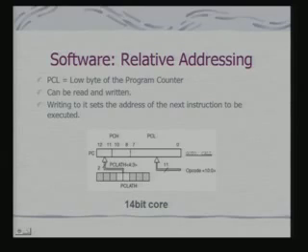So, whatever offset is coming, which is an 11-bit offset that is part of the instruction, all your goto and call operations are PC relative. This is the key significance of the fact that the most significant bits are coming from the PC latch high register.